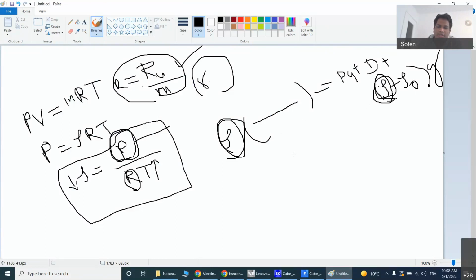That's why, during the Boussinesq approximation, we assume the density is a constant. Suppose we put it equal to 1.1; air density may be 1.1 if you do the experiment around 25 or 26 degrees centigrade. But someone is doing an experiment at some high temperature, say a furnace around 600 degrees centigrade, so the reference density is different, right?